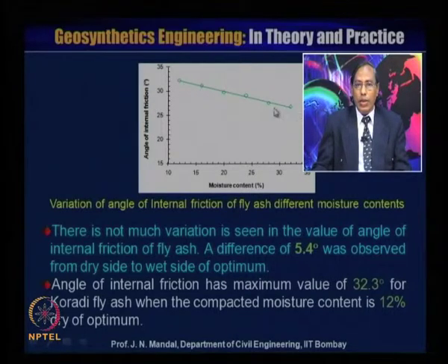The angle of internal friction is reducing with increasing moisture content, but there is no significant change. The only difference is 5.4 degrees, which is observed from the dry side to the wet side of the optimum.